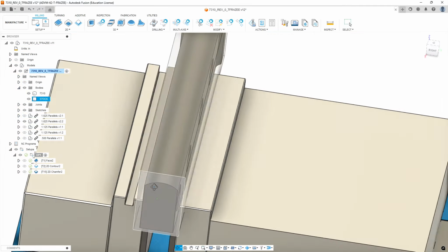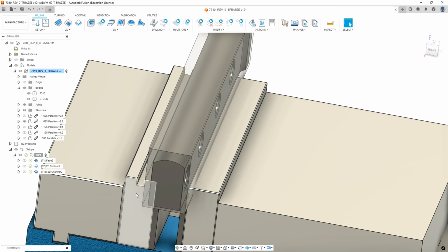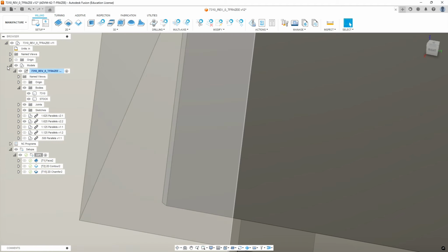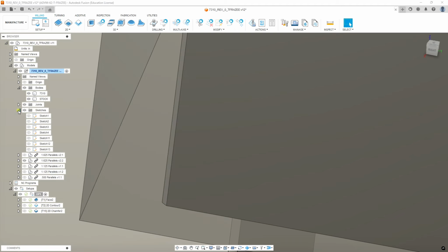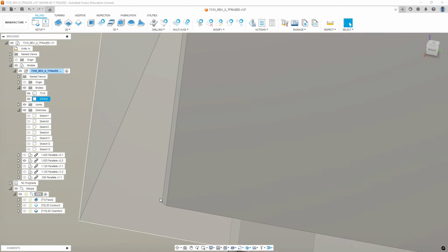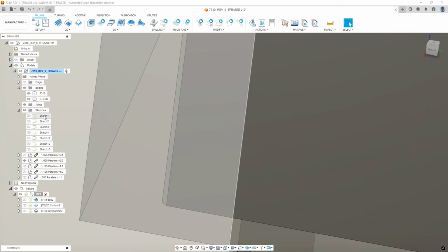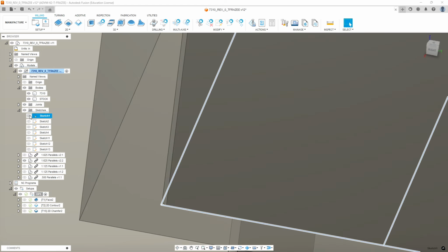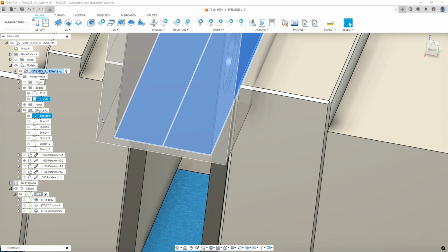In this case, we want our origin to be placed on the fixturing in the corner. And what we have is a chamfer here that won't allow us to select that corner. We can do selection, but we need to create something that we can pick on there. So what we can do is go back to our model. If you made this model roughly how I did, this was based off a sketch and the chamfer was added later. So if I go to my first sketch, it has that intersection. So I'm going to make the sketch visible, just temporarily.